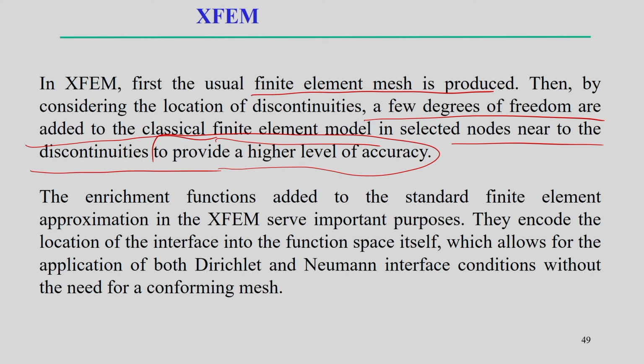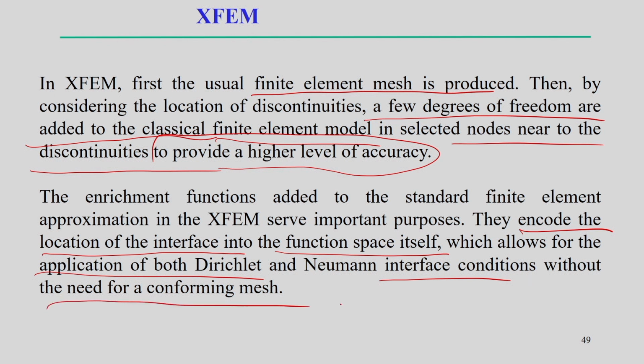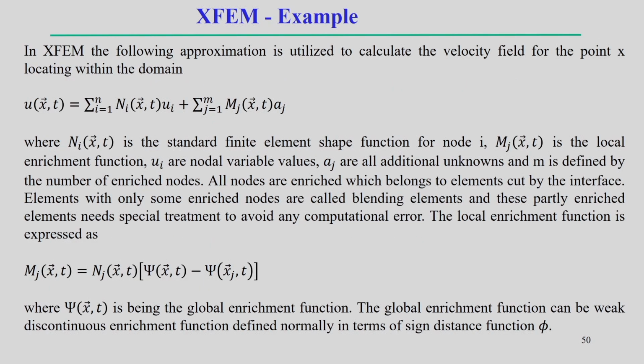So, the enrichment function added to the standard finite element approximation in the XFEM, the extended finite element method, serves important purposes. They encode the location of the interface into the function space itself, which allows for the application of both the Dirichlet and Neumann interface conditions without the need for a conforming mesh. It means that it is not necessary to have a conforming mesh exactly on that. Once the enrichment functions are added, it may not be necessary to follow a conforming mesh, such that XFEM can be used as an approximation to calculate, for example, the velocity field at a point x located within the domain.